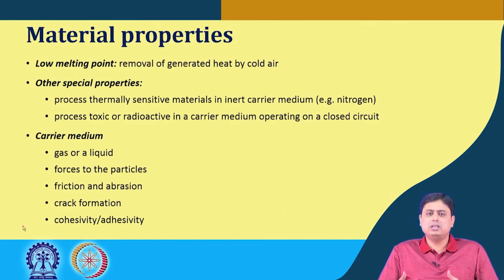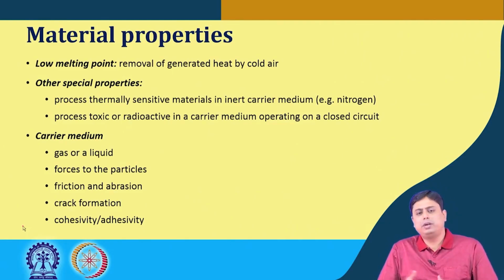It totally changes the hydrodynamics of the flow. Moreover, there is the influence of the carrier media on crack formation: does it make the solids more brittle or tougher? Depending on that scenario, we have to choose the size reducing equipment.